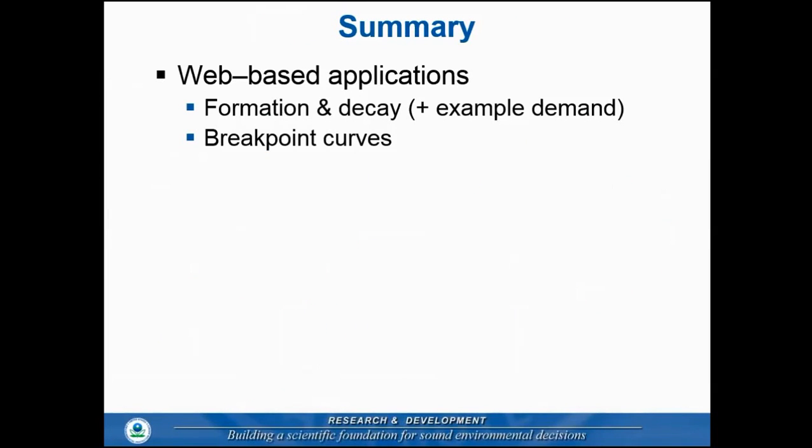And so that quickly went through a couple web-based applications. Again, the first one is really just to simulate formation and decay of chloramines, plus to provide an example demand reaction to show you what happens if there's other things in the water that are going to take out your chloramine. And the second one was just to be able to generate breakpoint curves for a given condition and reaction time, essentially. These, again, are free and online, and they're available for use.